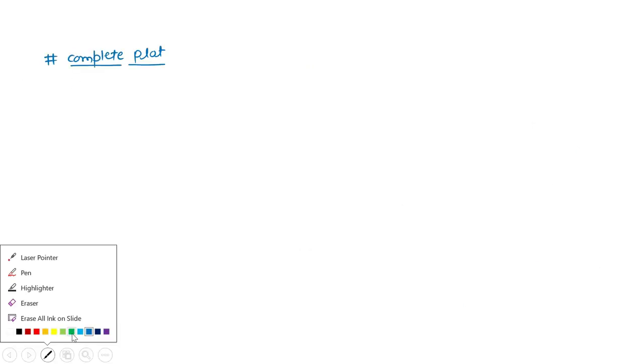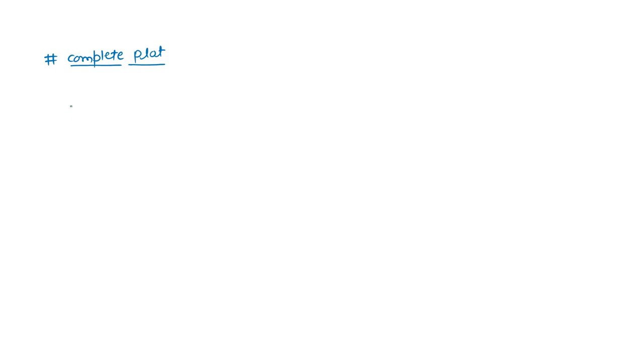Okay, so what will be the complete plot? Now come to the complete plot. So we have seen that, as I told you, this is much larger. So from 0 to 5 volt, and after that it is staying at 0 forever. Okay, so this is the time instant. So what was happening here? As my RC is much smaller, the capacitor initially charges and reaches faster, somewhere here, and is settled to 5 volt. Okay, and after that it is coming down to 0 and is settled to 0 volt.